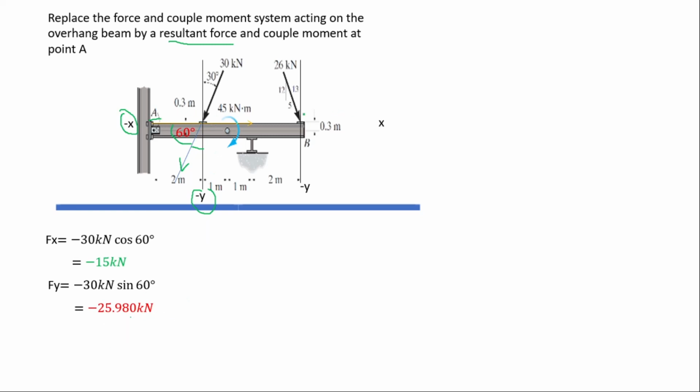Let's check this other force. Using the principle of transmissibility, we can transfer it and it will come down here. This is the force here now. But this angle is made with this, and normally we work with the angle made with the x-axis. So actually we are going to use a different diagram. You draw a different triangle, with this as the hypotenuse. So the hypotenuse is 13, the x component is 5 and the y component is 12.